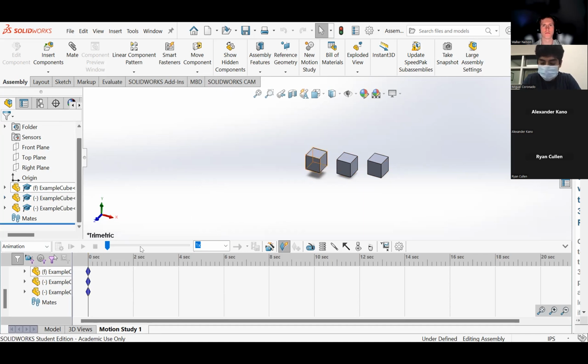So now I want this to be, let's put this at 5 seconds. So what I'm going to do is go over here to this top part of half of the screen, and I'm going to click on 5 seconds. These things that you see here, Animation Wizard, we're not going to go into because that's not the focus right now. Leave on auto key, we're going to use it. Motor, your spring, you have a damper, you have a force, you have a contact, and you have gravity.